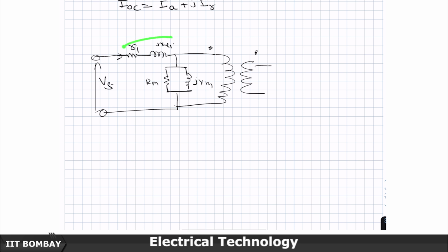But because these drops are small, almost this same voltage is getting impressed across the winding. The flux levels really don't change much. The currents which are drawn here are literally the same, close to the open circuit current values, and the losses in the core are almost the same, they are not really changing significantly.